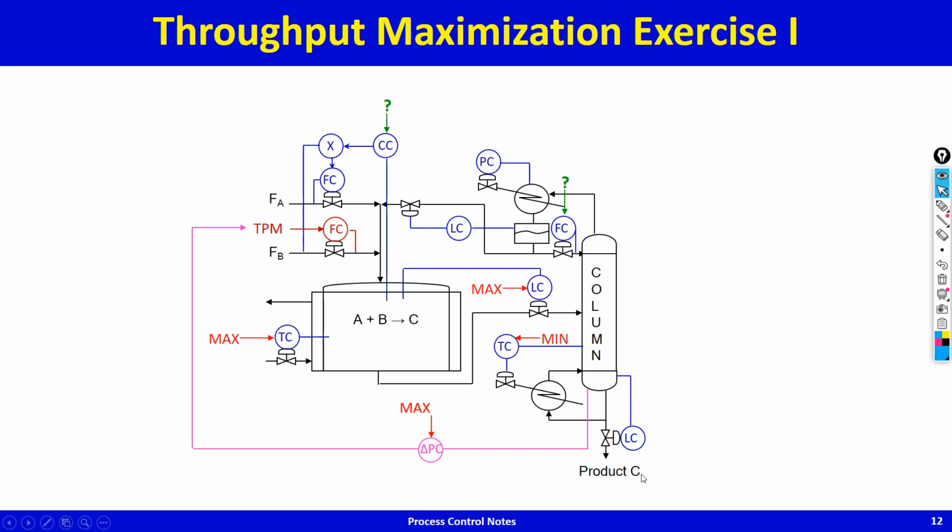You would like the delta P to be at max for maximum production rate, however the loop is long, dynamics is going to be very slow. Because the dynamics is slow, the control cannot be as tight, and therefore because of this long loop you will have a large back off, because this max limit cannot be breached.